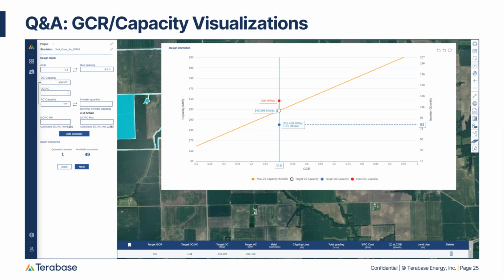So if you put a number in the minimum, no inverter on your site will go below that minimum. And then the same thing for the maximum. So if you put a maximum value in there, every single inverter will have to adhere to that maximum, and no single inverter will go over that DC-AC ratio or inverter loading ratio maximum.